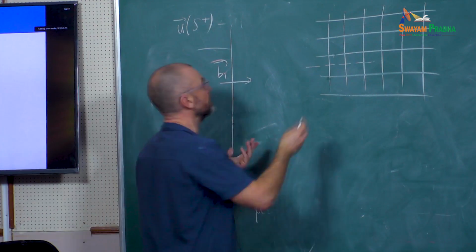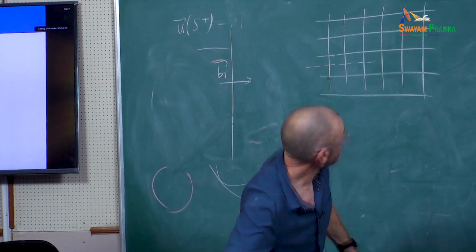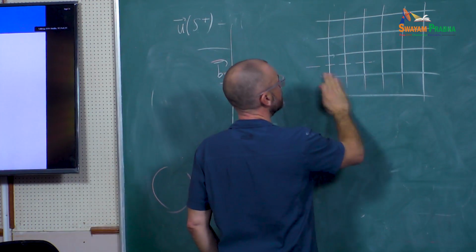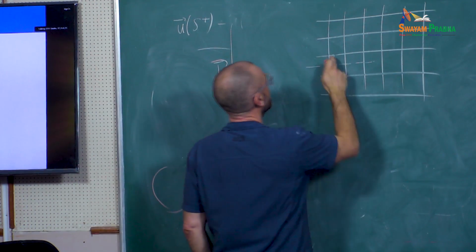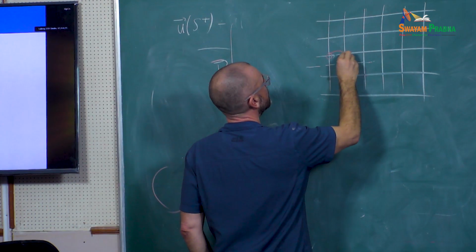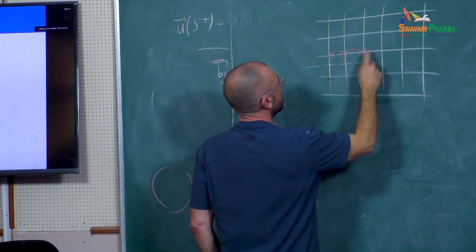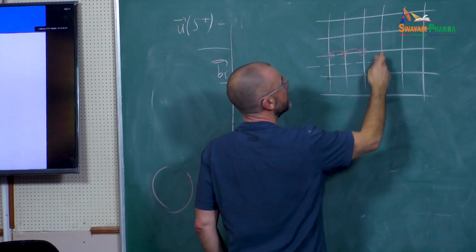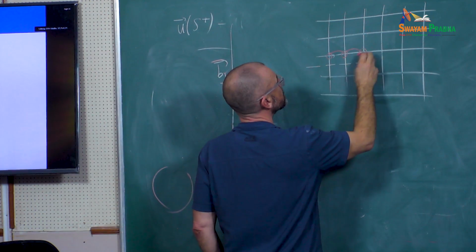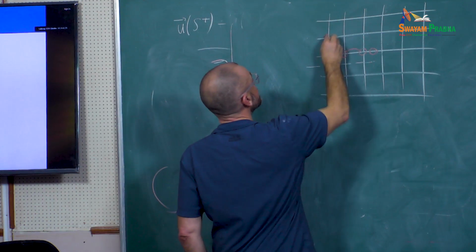So what is the smallest vector I can use as a Burgers vector? It's the spacing, because if I do that, then, assuming that I do not move what is at the bottom, this atom here, by the shear process, will go here. The atom that was here will come here. This one does not move if I stop here. The atom that was here will come somewhere around here. And I do the same for these atoms here.